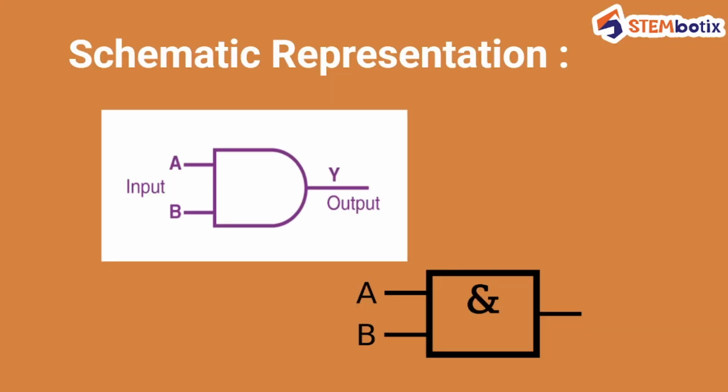So this was the operation for AND gate. It performs the AND operation, means A and B both are there, then and only then you will have output. While OR gate performs either-or condition. If either A or B is non-zero, still you will have output. While in AND, it performs AND operation, means if and only if A and B both of them are in state 1, will give you output as state 1.